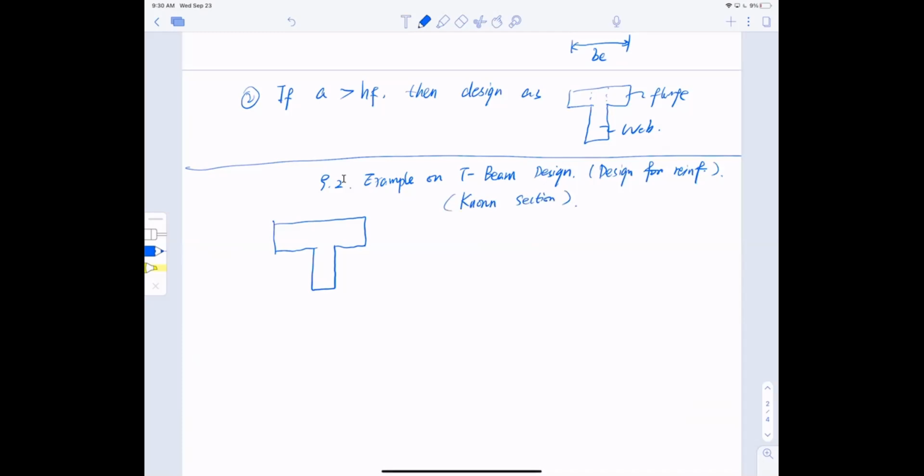So let's get back to the geometry. I have a T-beam, and the flange width is 47 inches. I have a web width, b_w, a very odd number, 11 inches. I don't know how much steel I have. I have a fixed depth of 20 inches, and a flange that is fixed as well, 3 inches. So the distance from the bottom edge of the flange down is 20 inches; in other words, h is 23 inches. This is my geometry.